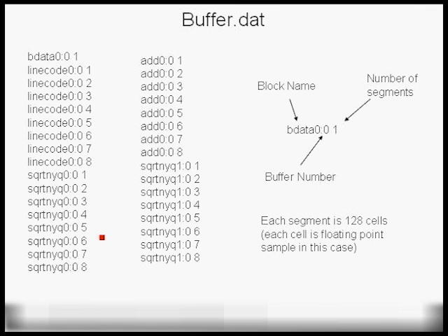Also, the square root Nyquist filter allocates 8 segments for its output, and so does the add block, and so does the square root Nyquist filter at the receiver. So in the case of multi-rate signal processing, we see that the memory footprint will actually increase to accommodate the multi-rate signal processing. Now this is not an issue, especially in the case that even though we generate, for example, gigabits, the footprint doesn't increase and will remain as shown over here, regardless of how many bits are generated.